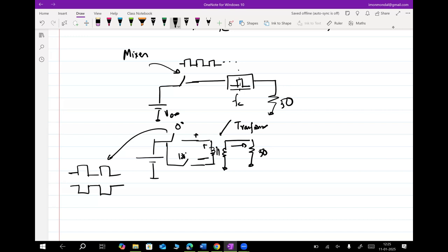So what is the moral of the story? The moral of the story is PAs are a major bottleneck in an RF transceiver. People have been trying to build different types of PAs for a long time to increase the efficiency. Efficiency of a linear PA is much poorer than that of a switching PA. You can make switching PAs in theory. Theoretically, you can make switching PAs with efficiency of 100% in theory, right?